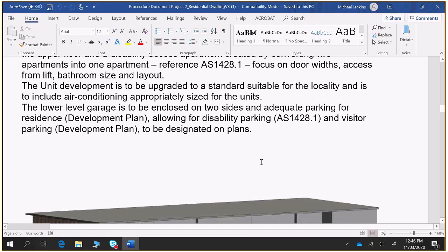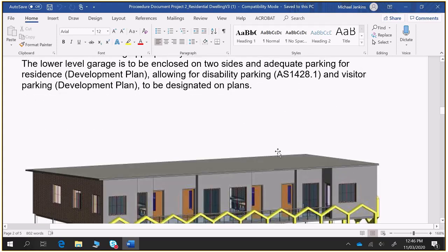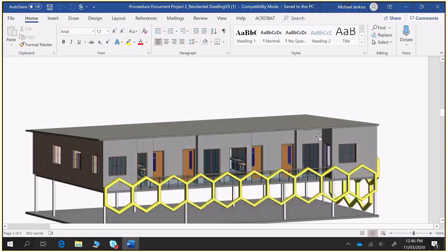So through this process, you'll be working out what you can do to renovate this block of flats. You'll be looking at ensuring there are fire separation walls between each. Now, we can't go on site and inspect. In fact, this building doesn't even exist, and the site, as you get it from here, doesn't actually exist either. We'll give you an address, but you're going to have to put in notes to say that these fire separation walls meet the required FRLs for that class of building.